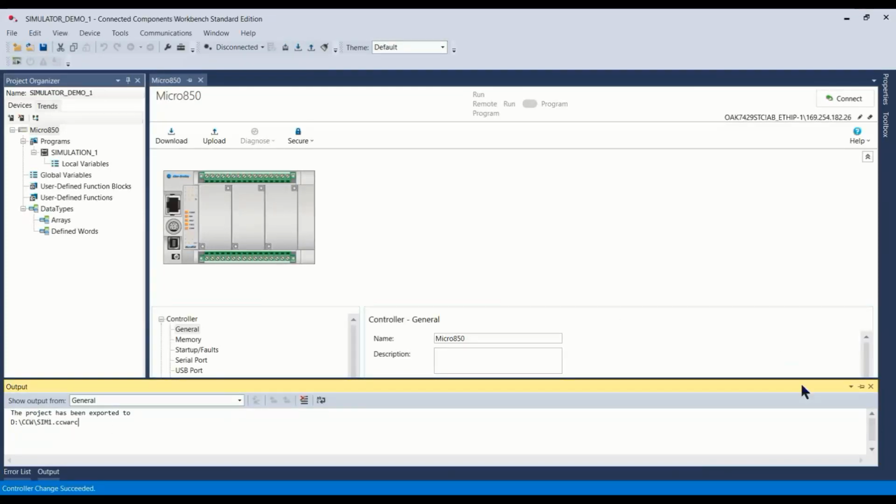And that's basically it. So you can see how we start the simulator. There's a couple of tricks that we can do to prevent faulting it out. And when you're working with it, in any situation in the class, if you're going to relate it to the trainer, make sure that 3, 7, and 13 are turned on to simulate the normally closed contacts.